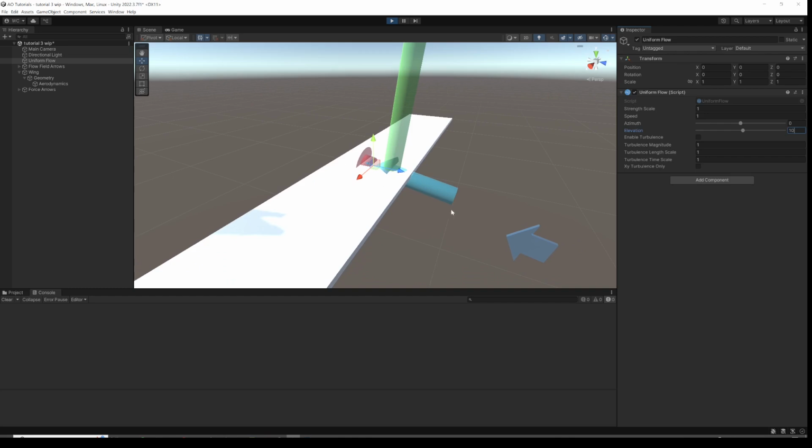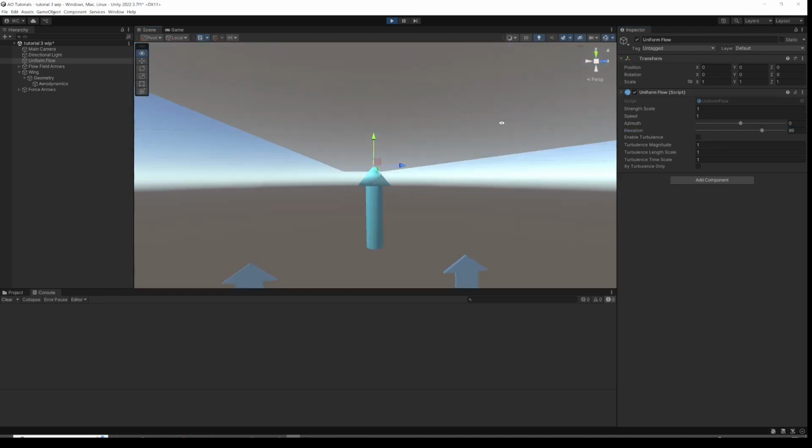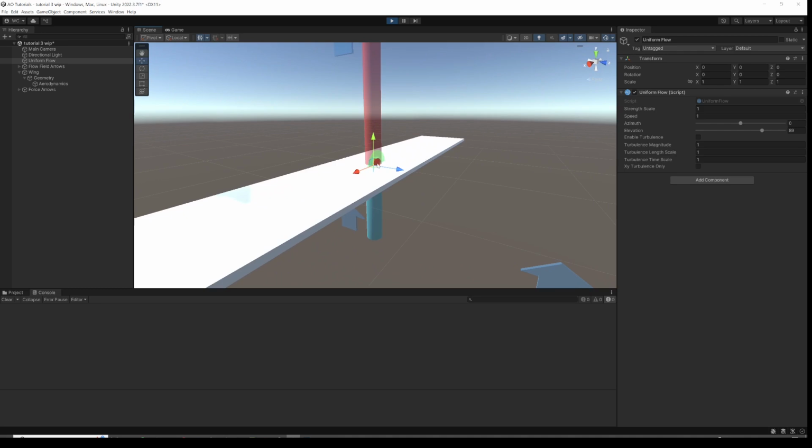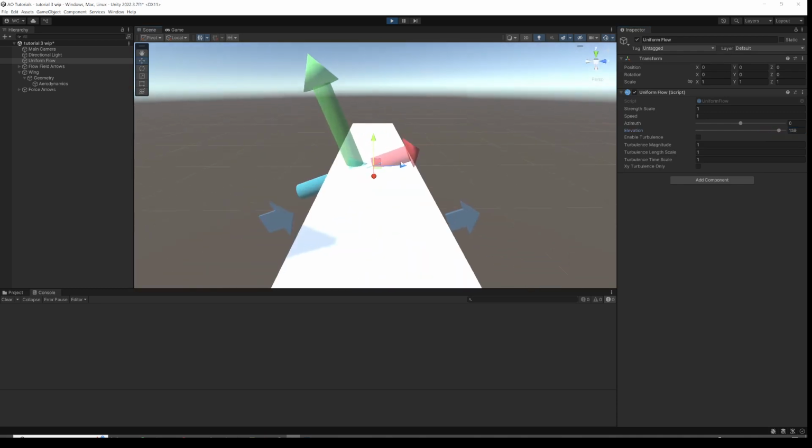the leading edge. But if we increase the angle of attack, what you see there is the aerodynamic center position moves back until we get to 90 degrees angle of attack, and now the lift, or what's left of it, is acting at the center of the object. And if we keep on going round and the wing is going backwards, that aerodynamic center moves round to around quarter chord in the other direction.